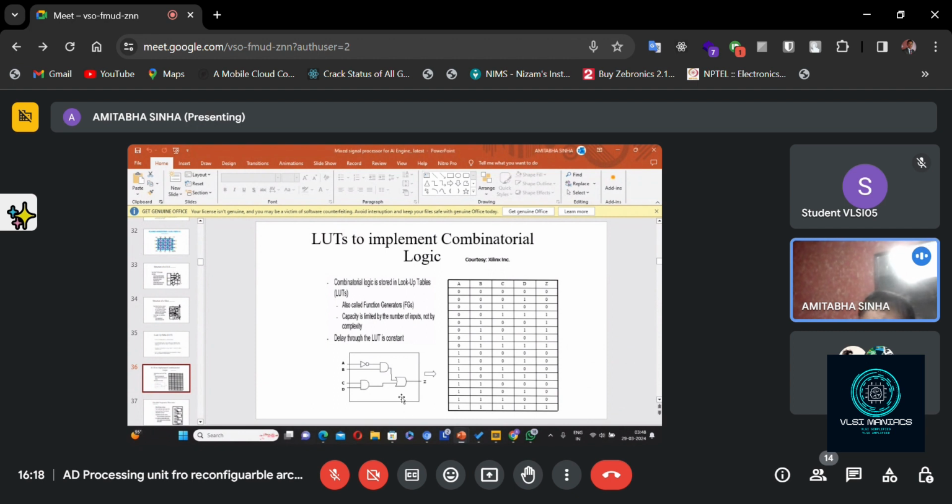Like here, let's say this is a typical logic function circuit. The functioning of this is placed onto the lookup table. So when you write a code in a high level language, what happens? These codes are transformed into a number of CLBs. The contents of the CLBs have to be defined for making a particular function, and how these CLBs will be interconnected.